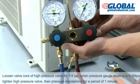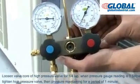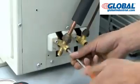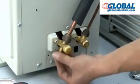Wait 1 minute. Check the indicating of pressure gauge. There should be no change. Open fully valve cores of high pressure valve and low pressure valve. Tighten valve cap.